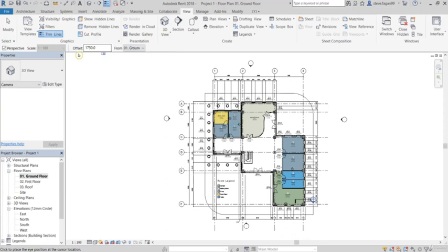Here we have our options bar, where our first thing is the perspective. So when we're creating a 2D view, we want it to be realistic and have perspective. So yes, we want that to be turned on. If we turned it off, the view that we'll get will be the same as if we were to use our default 3D view. When it's turned off, you're able to specify a scale. That's why we can't select it at the moment.